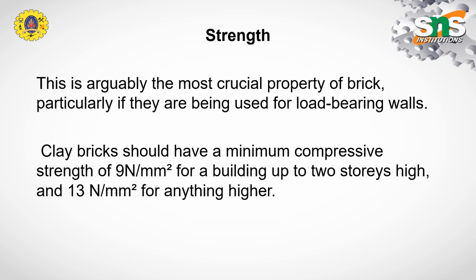To build such walls, the clay bricks should have a minimum compressive strength of 9 newton per millimeter square for a building of two stories. If it is above a G plus two-story building, then the compressive strength should be greater than or equal to 13 newton per millimeter square.